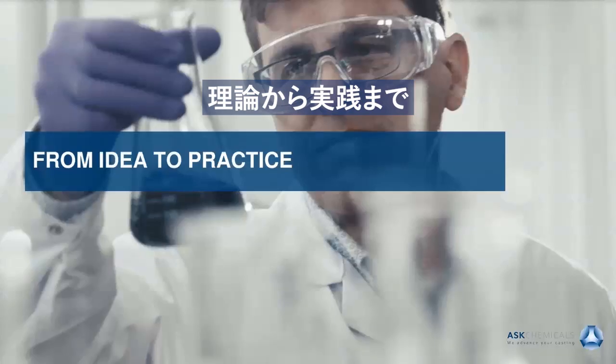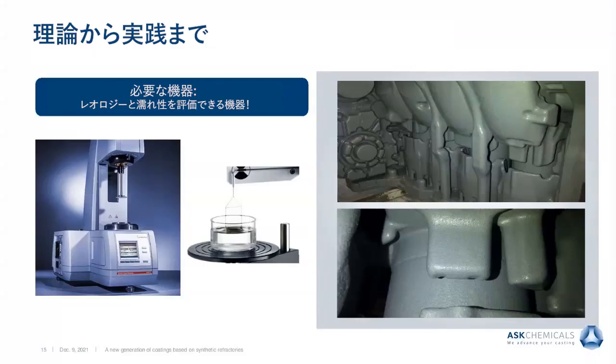How do we come from the idea to practice? We have very sophisticated instruments in our laboratories, for instance, doing rheological measurements or measurements with a tensiometer to control and adapt the flow behavior and the wetting behavior of the coating.